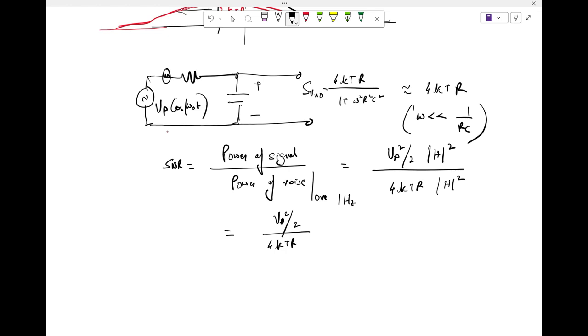So in this scenario, I have modeled the source as an ideal source with no resistance associated with it. But in principle, there will be some resistance. And if you draw more and more power, that is, you are drawing more and more current, you are going to see a drop across that resistance. And hence, you will see all the voltage drops across everything, right? So your circuit will not function as it was meant to be.